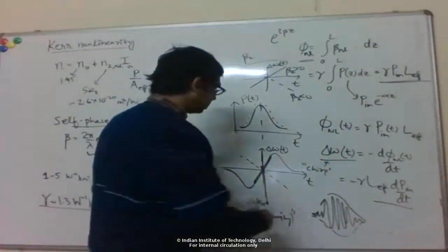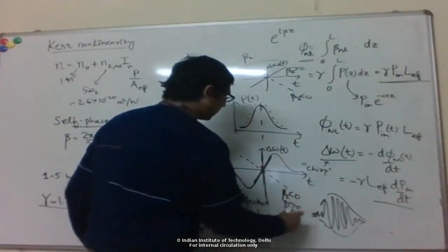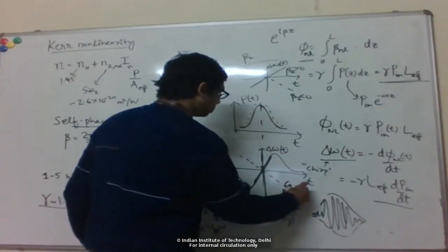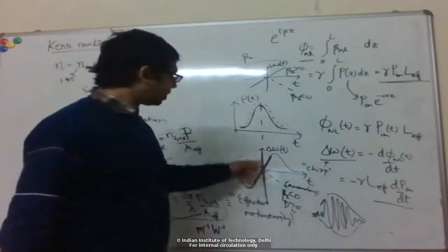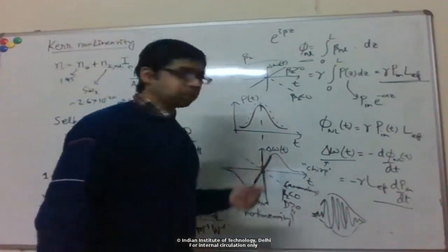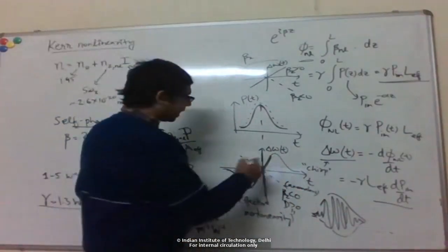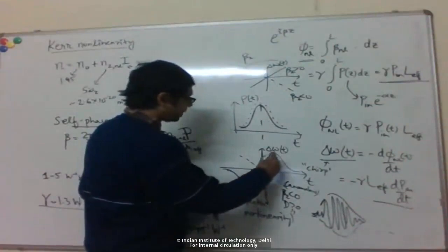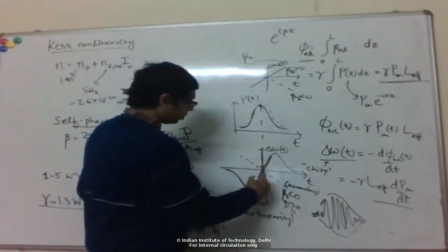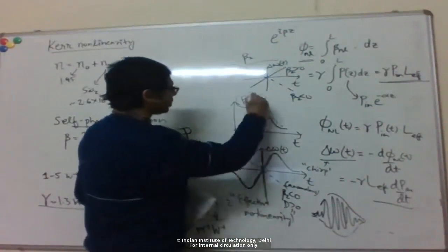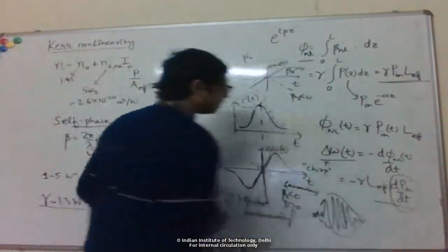So for an anomalous dispersion fiber, beta 2 less than 0 or D greater than 0, you can see that the effective chirp when we add these two will actually be smaller. And you can even imagine that if I set things up right, of course this depends on the pulse power, the slope here for the nonlinear chirp depends on the power. You can see it's the derivative of the power.